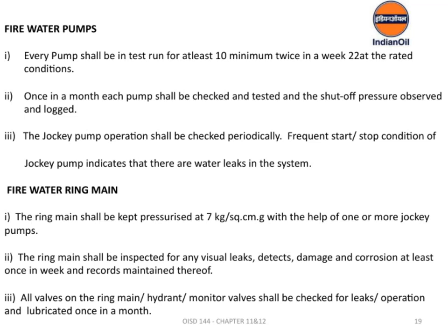Let's go over the key points related to fire water pumps as per OISD 144, Chapters 11 and 12. First, every pump must undergo a test run at least twice a week for a minimum of 10 minutes each time, and this should be done at the rated conditions. This regular testing ensures the pumps are functioning properly and can deliver the required pressure during an emergency.